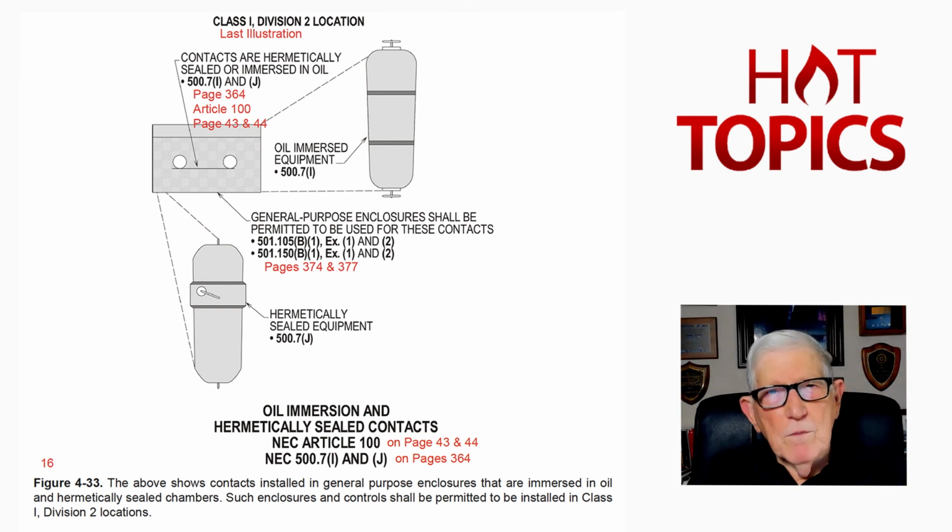Now, what is the difference basically in intrinsically safe, or non-incendive? Is that we have a barrier that creates a safe zone where damaged wiring and components has no effect to cause an explosion. Where non-incendive must be used under normal operating conditions, no damage to wiring, and no damage to components. Now there you have it.